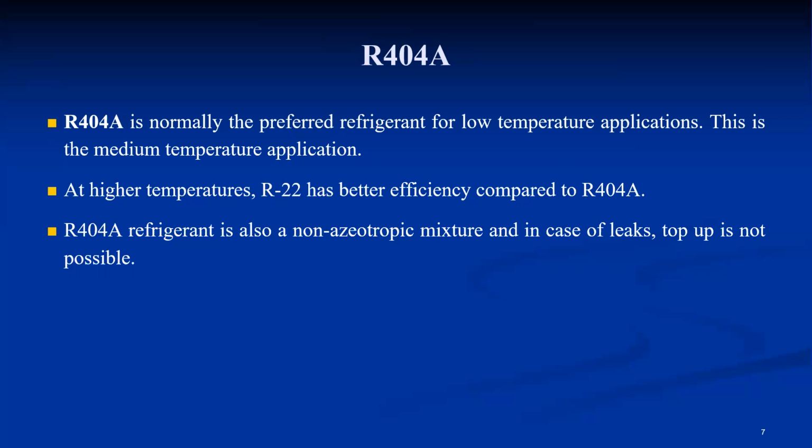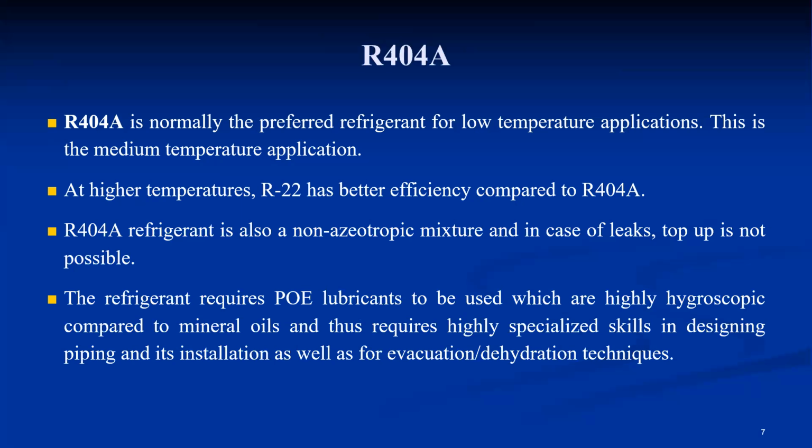So these refrigerants, especially non-azeotropic mixtures, are not at all suitable. In case of a leak, the entire refrigerant has to be replaced with new refrigerant. The top-up is not permissible. So these are some causes where 404A is also rejected. And the last one, it mainly requires POE lubricants, which are highly hygroscopic compared to mineral oils. It has an affinity to absorb moisture.